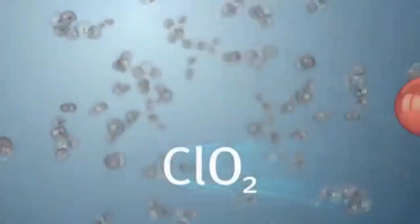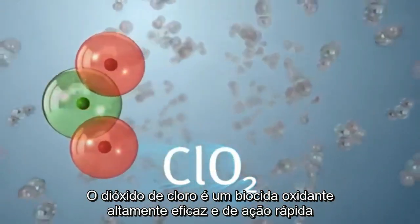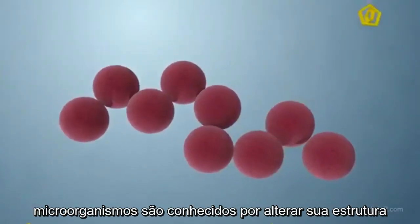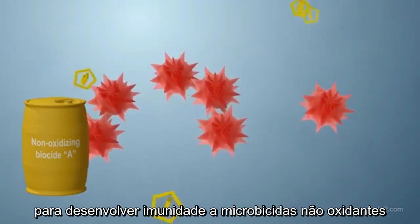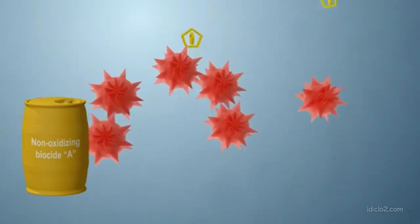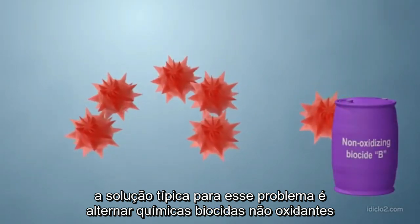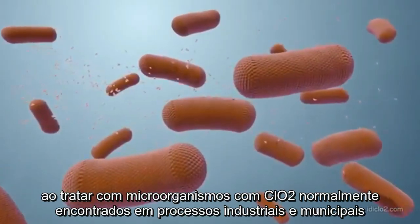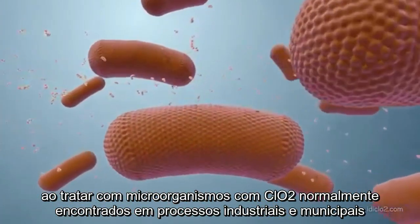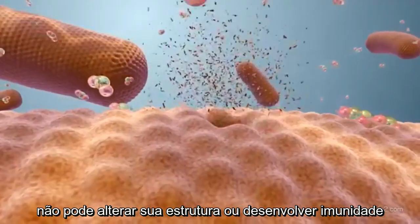Chlorine dioxide is a fast-acting, highly effective oxidizing biocide. Microorganisms are known to alter their structure to develop immunity to non-oxidizing microbicides. The typical solution to this problem is to alternate non-oxidizing biocidal chemistries. When treating with ClO2, microorganisms typically found in industrial and municipal processes cannot alter their structure or develop immunity.